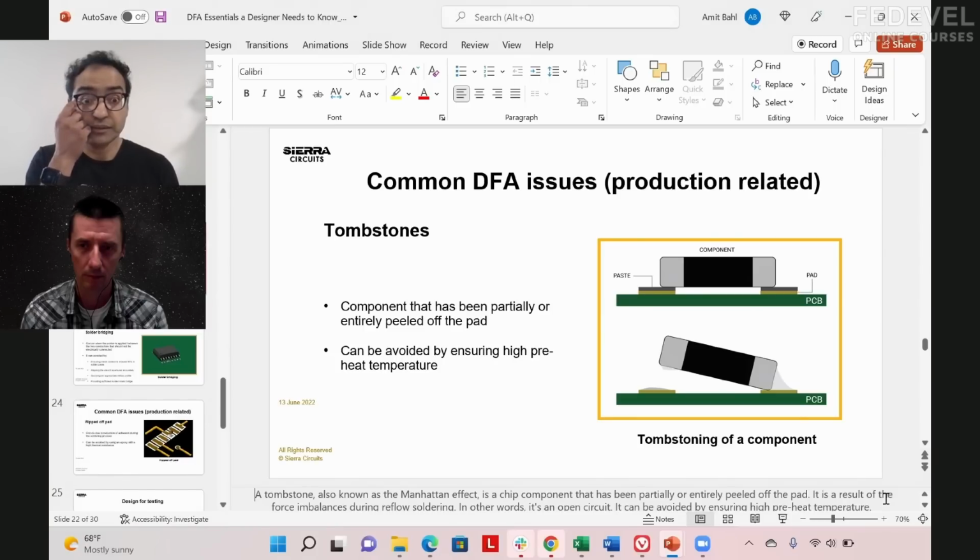The first is I would review with your vendor before you actually manufacture. So, not just send the PCB data, but assembled boards? Both. Review everything before you manufacture because you might have a chance to fix some things before manufacturing, which is good.